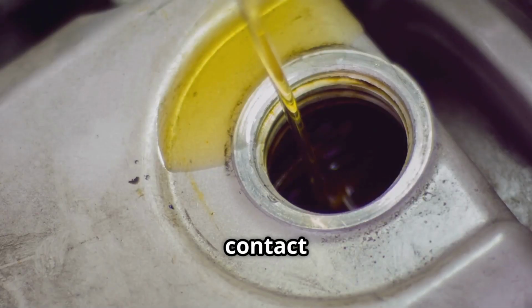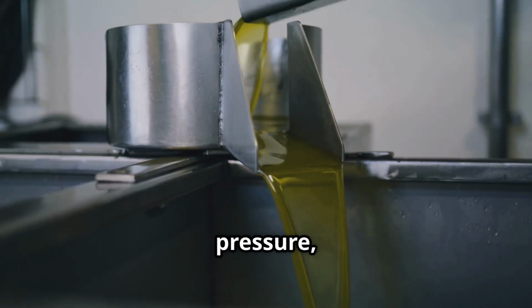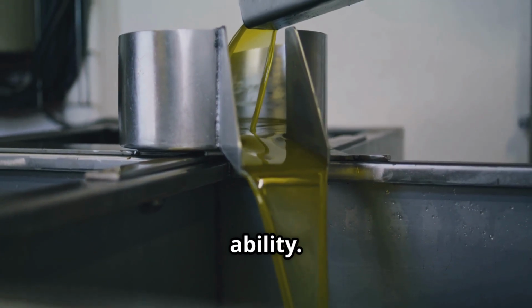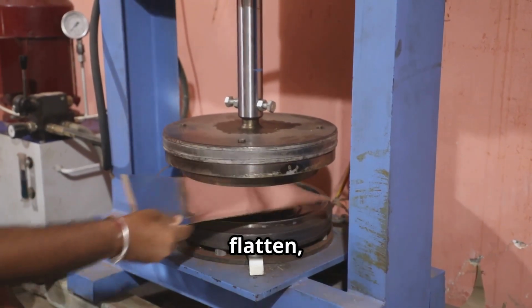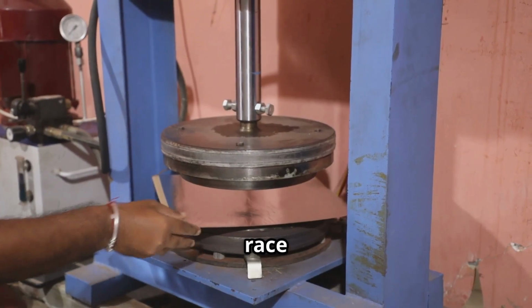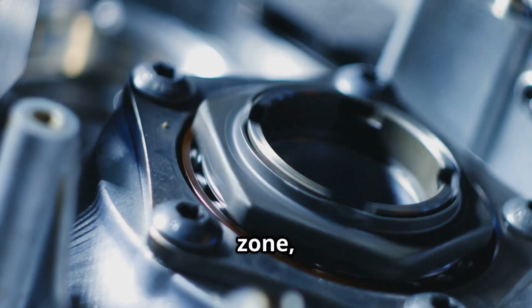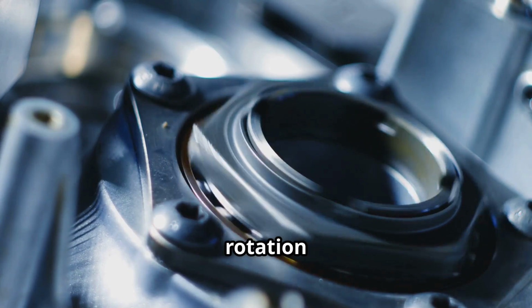As the oil enters the contact zone between a ball and raceway by rolling action, the oil's pressure rises sharply. This high pressure in turn significantly increases the oil's viscosity and load-holding ability. This concentrated load will slightly deform, or flatten, the metal of the rolling elements and race in the contact zone. The deformation only occurs in the contact zone, and the metal elastically returns to its normal form as the rotation continues.